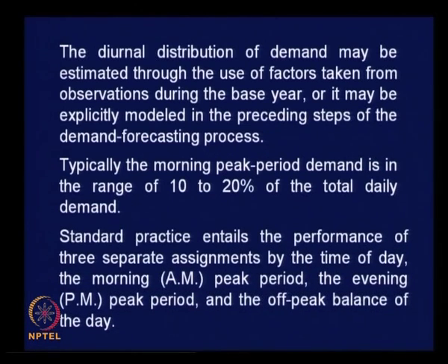Standard practice entails the performance of 3 separate assignments by the time of day: the morning AM peak, the evening PM peak, and the off peak balance of the day. You have to do assignment for 3 traffic demand situations.